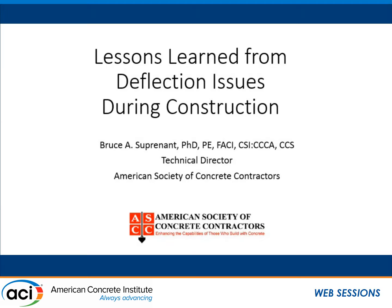and that really helps. The other thing, if we follow what ACI 347, the formwork committee, says about how we're supposed to design formwork, we will crack the slab based on that. And I wish that committee maybe could take some help from 435 or some speakers here and would actually put it in the document, because what they say is high loads or excessive loads will crack the slab, which makes everybody believe if they see a crack, then we've done something wrong. So it'd be nice if that perception was worked with.